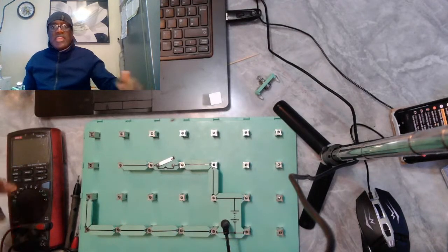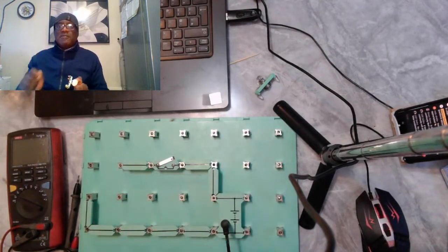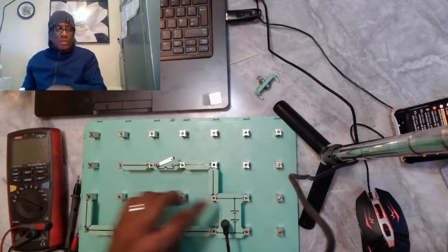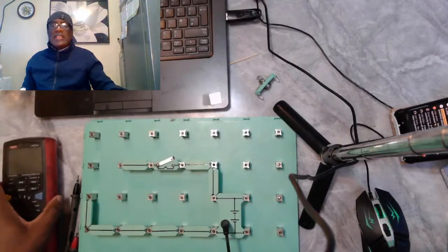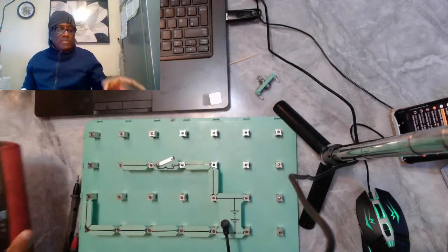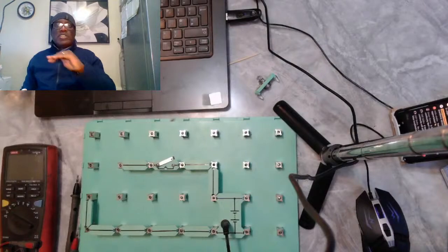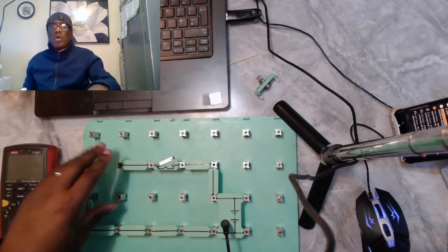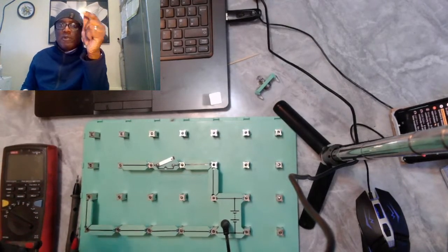If you check resistance on a live circuit, now you have got two batteries. You have got this 12 volt, and then this 9-volt battery that is in here. Something has got to give in. Your 9-volt battery will give in and you damage your meter. So when you're checking resistance, gentlemen, don't check resistance when a circuit is live. When you want to know the effect of resistance in a live circuit, you check for voltage drop.